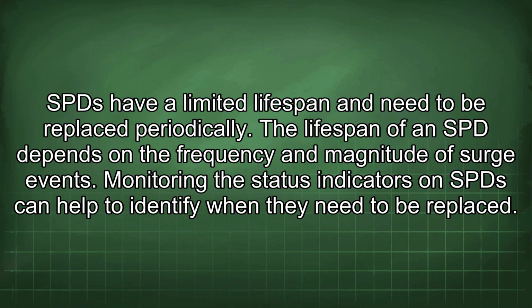SPDs have a limited lifespan and need to be replaced periodically. The lifespan of an SPD depends on the frequency and magnitude of surge events. Monitoring the status indicators on SPDs can help to identify when they need to be replaced.